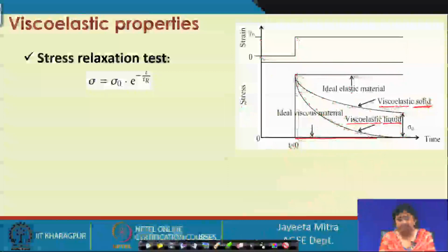Whereas the material which has a high solid content compared to the viscous material, in that case some amount of exponential decay we will observe. However, it will retain some amount of energy. It will store some amount, and it will recover to some degree with respect to the elastic property in it. And sigma E, that is the residual stress, will remain there, that we can observe.